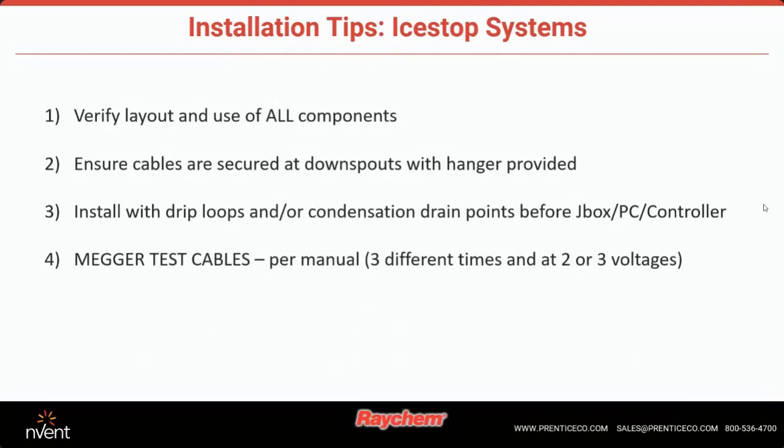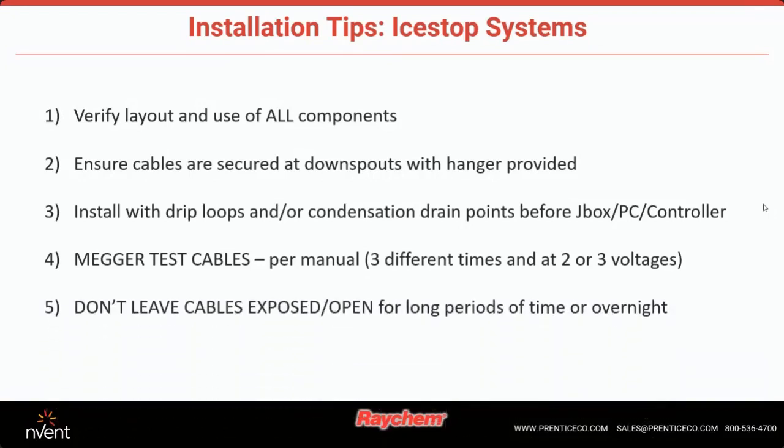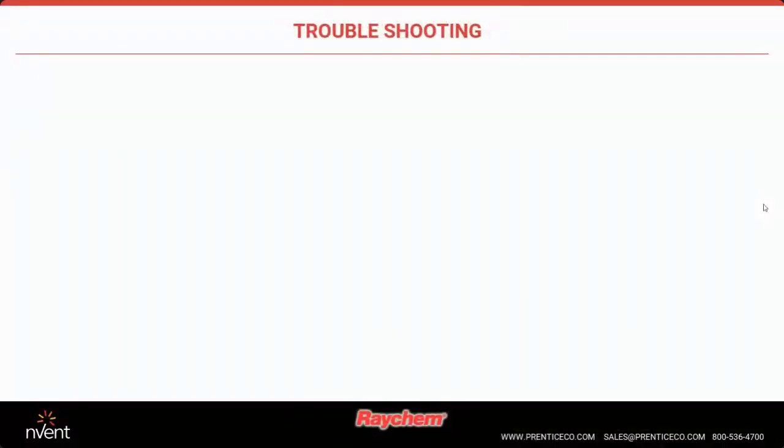Again, Megger testing the cable. I can't express this enough. This is very, very important, and making sure you follow the manual and guidelines to do that. And don't leave the cable exposed. Again, this is another very important tip, which is why I'm putting it on all these slides.